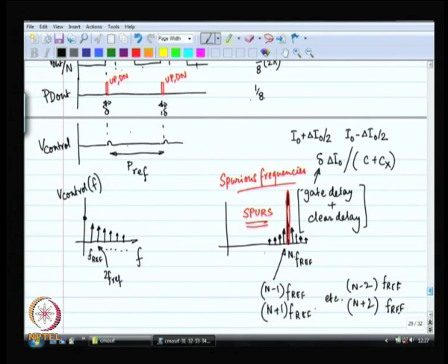Now, because up and down have these small glitches, and because it is impossible to perfectly match two current sources. Also note, one current source is a source, the other is a sink. Okay. So, they are not even of the same quality. One will be made with NMOSes, the other will be made with PMOSes. It is very hard to perfectly match an NMOS and a PMOS, it is not possible.